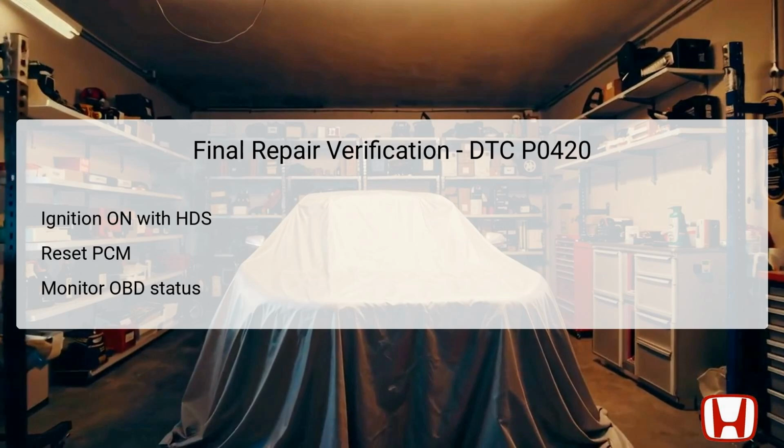After the learning procedure, the engine should be started again and the RPM held at 3,000 without load until the fan engages. A test drive under the previously outlined conditions must be executed once more, and the OBD status should be monitored for any return of the P0420 code. This thorough verification process assures that the repairs were successful and that the vehicle complies with emission standards.